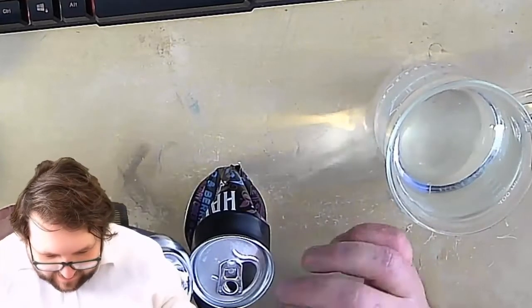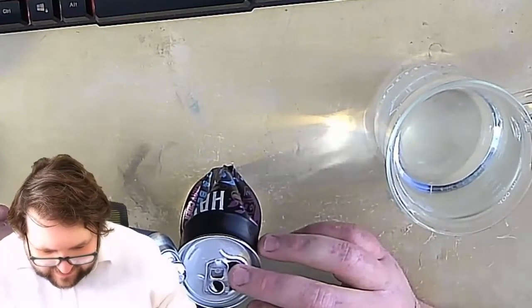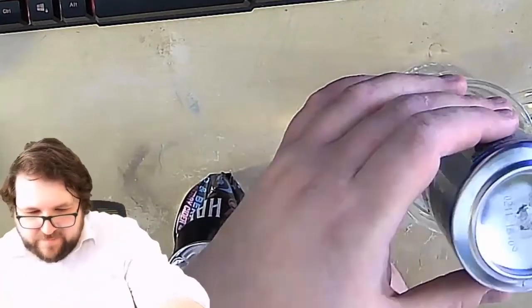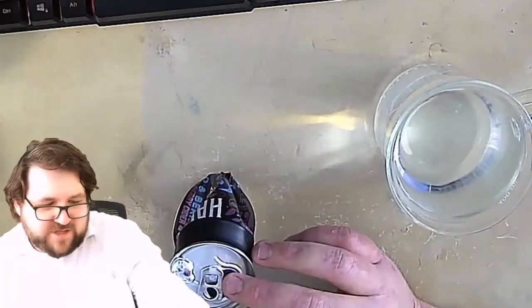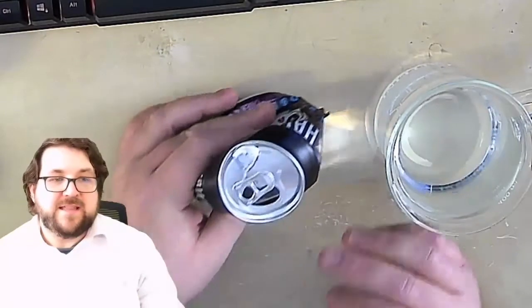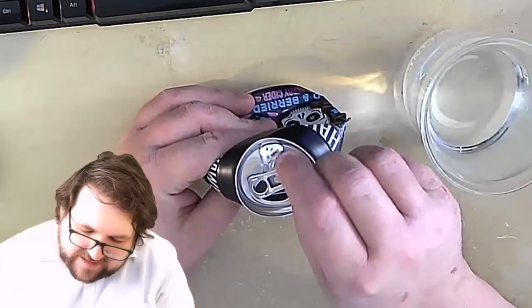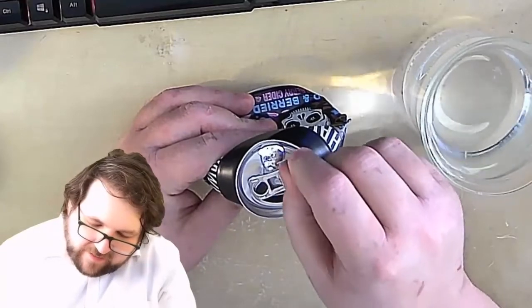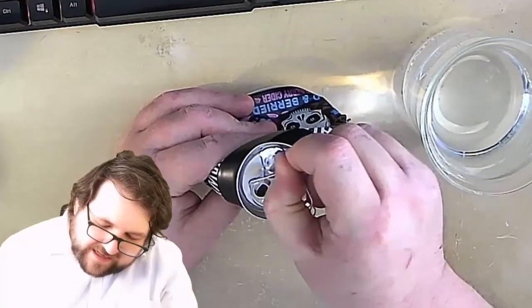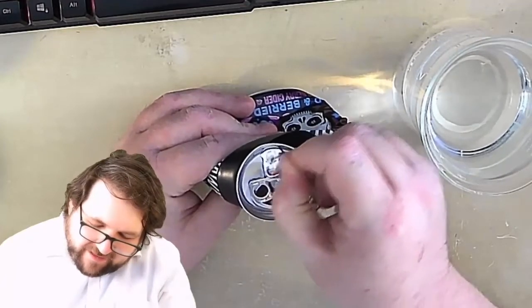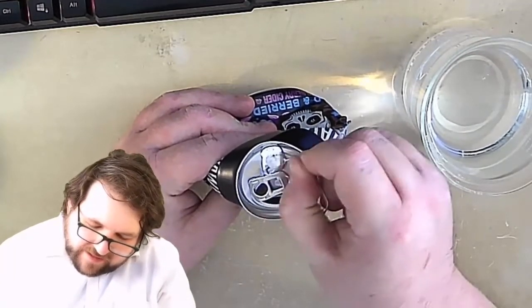Okay, now I'm going to pour the gallium onto the aluminium can, ideally not down the hole. Lovely. I'll leave that for future me to sort out. And then here, with the gallium on the can, what I'm going to do is scratch the surface. Now, the reason for this is that the aluminium has an oxide layer. So I'm just using this to scratch through that layer and expose the pure aluminium to the gallium.